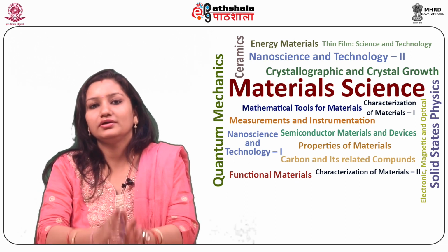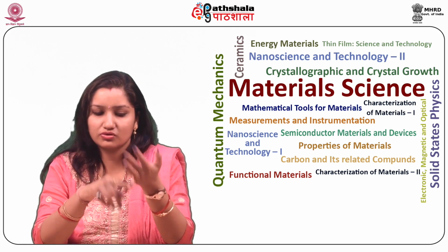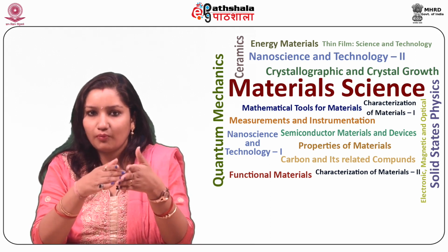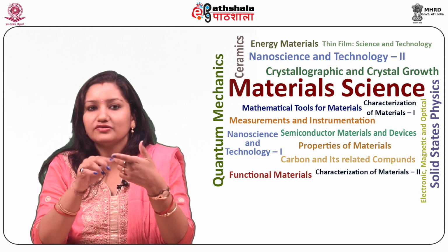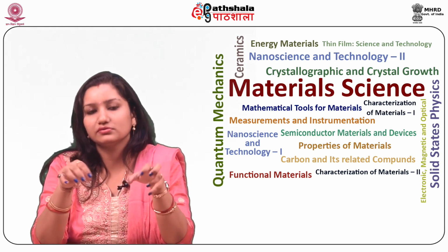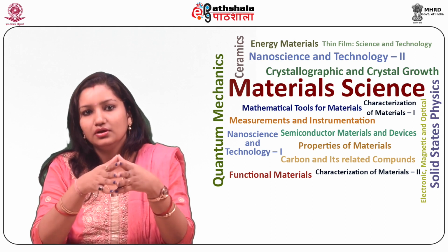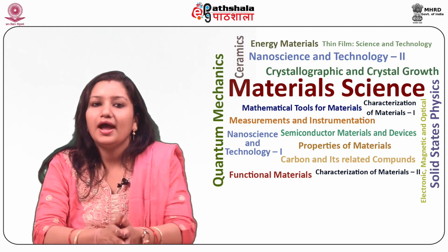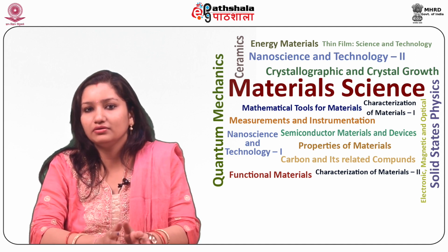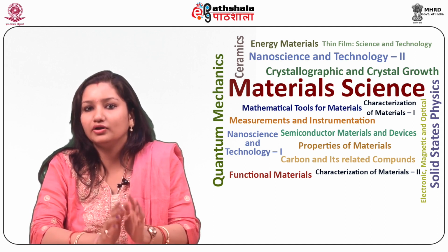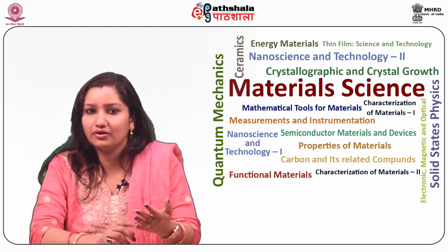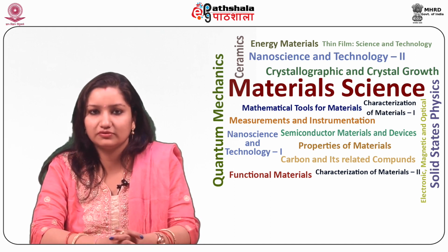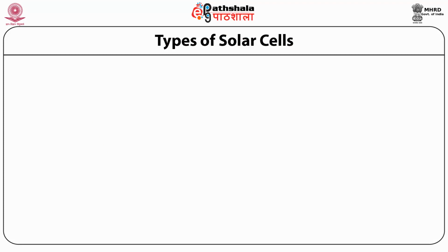Then in thin film solar cell, different types of junctions are possible: homojunction, heterojunction, Schottky type junction, etc. Then tandem and multi-junction cells are also possible using thin film solar cells. Next, in situ cell integration to form modules is possible using thin film solar technology. Then the thin film solar cells are compatible with solar thermal devices. And in the end, there is the ability of tailoring various optical, electrical and optoelectronic properties, for example, energy gap, electron affinity, work function, graded gap, etc. using thin films.